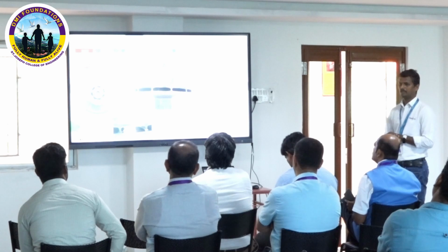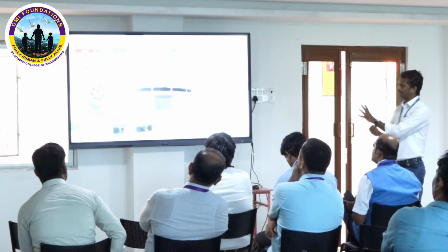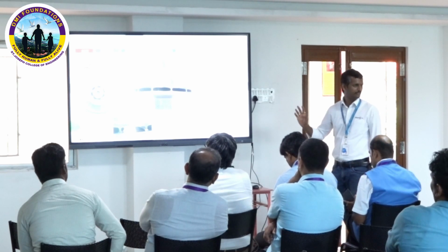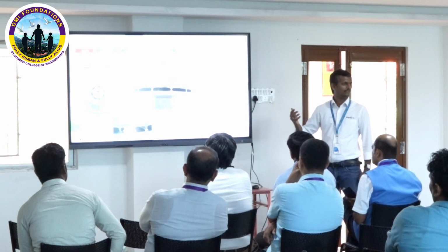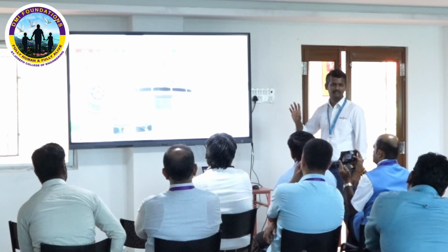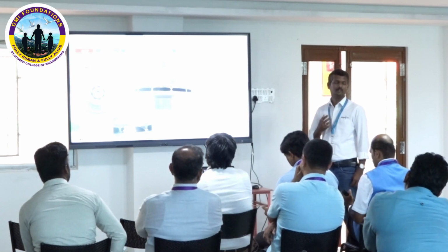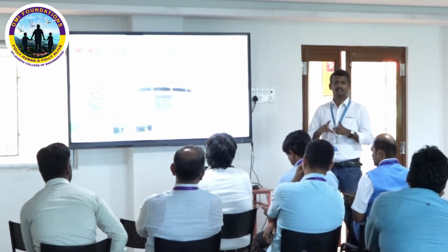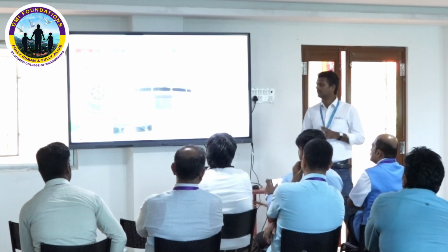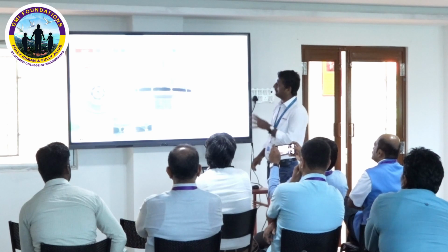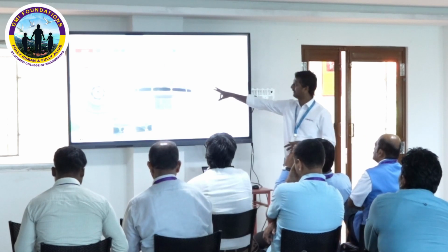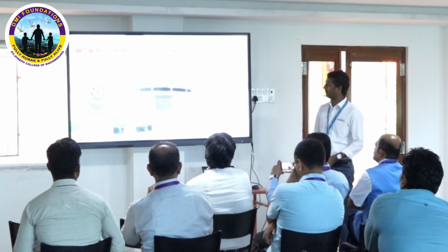This is a critical part, because if you try to print it, you will get support structures at any place. Design wise, we can't make any change because this is the best performing design. The pump is going to perform better with this particular design only. So design wise, we can't make a change, but we have to come up with the orientation in such a way that there are no supports, or even if supports are there, they are easy to remove. That's why we have done this particular component. It's again an AlSi10Mg component, and the diameter is around 130 mm and the height is around 87 mm.